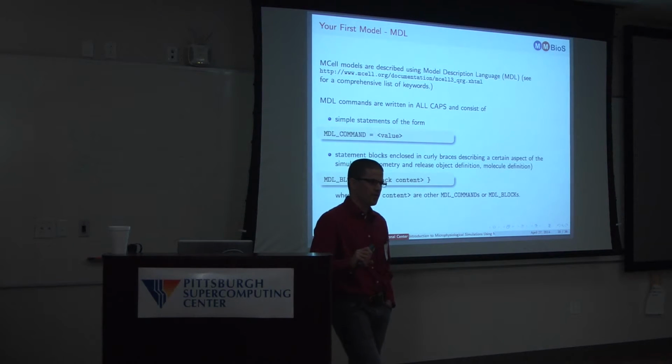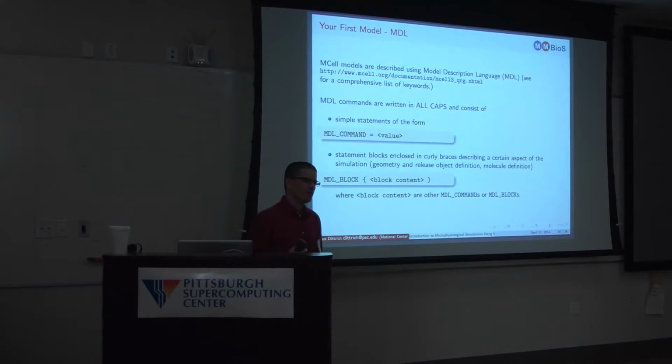So there might be a few parameters that, if you just double them, really have an impact on your model. Those would be the parameters you should think about most carefully. If you double one of your k values and you get a completely different result for your simulation, you would interpret the result differently. So this would be one to think about very carefully and really make sure that you got the right value here.